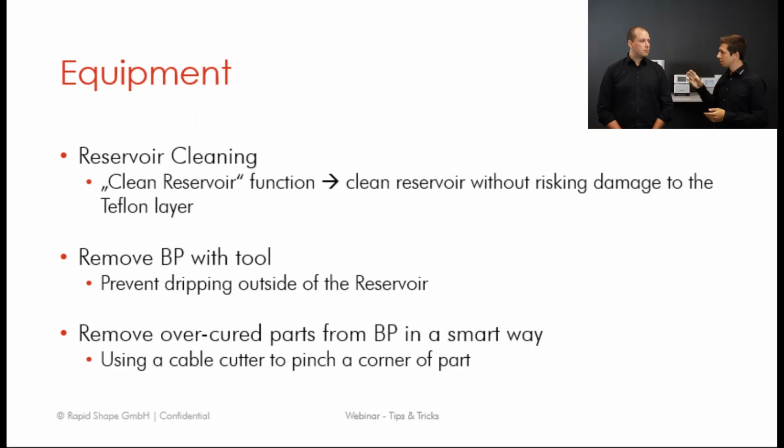I think you also got a tip in the first webinar regarding cleaning of the reservoir. So the idea behind it is, if you are swapping materials from one reservoir and you need to make it clean so that you can use a different material, use the clean reservoir function, so that when you're cleaning all the residual material out of that reservoir, you have no threat of damaging your print area, which is exposed during that show white or the clean reservoir function.